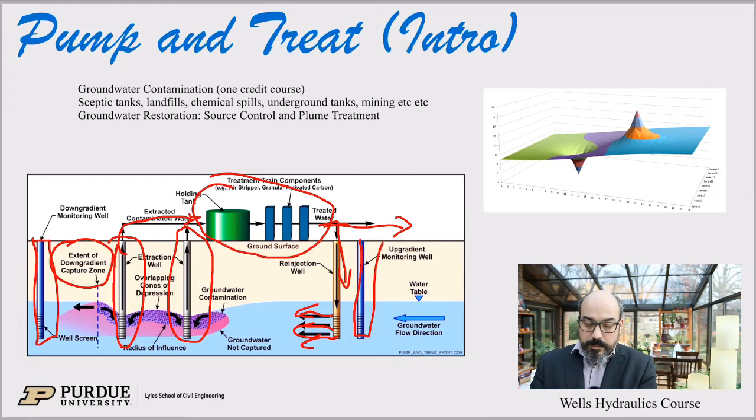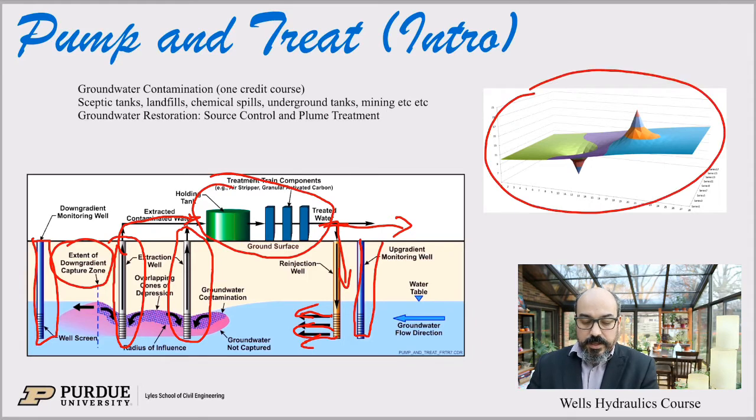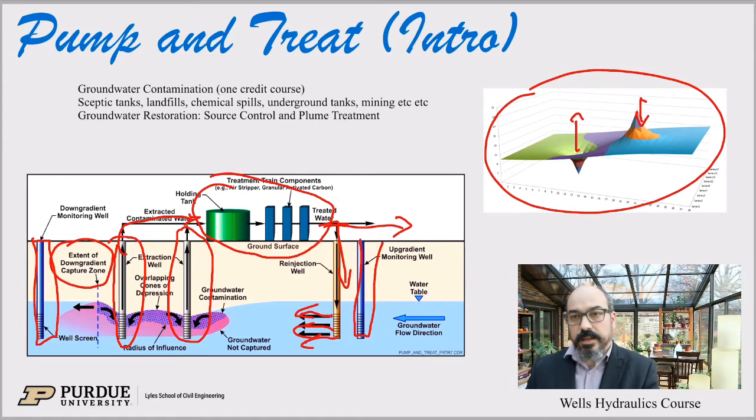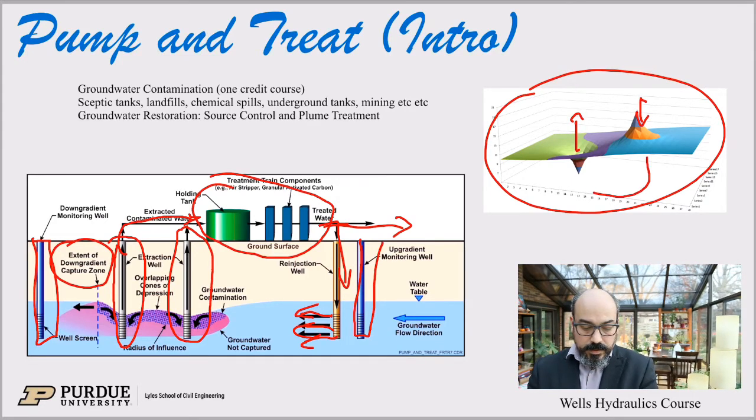Here, just as a reminder, on the right-hand side, I'm showing a well pair, similar to what we've done with our little Excel finite difference models, where you can see there's an extraction well here, an injection well here, and again, you can easily see how we create a cell underground, a recirculation cell, if you will, that can capture the water in that zone here.